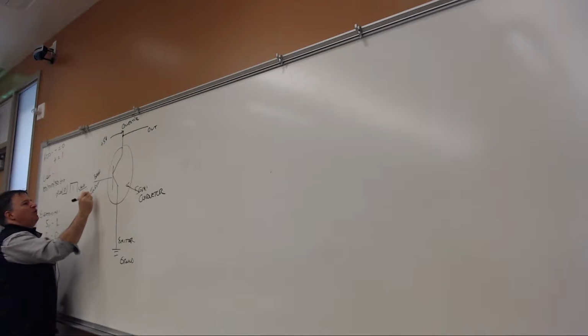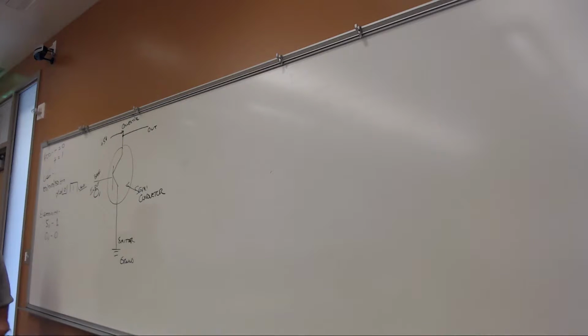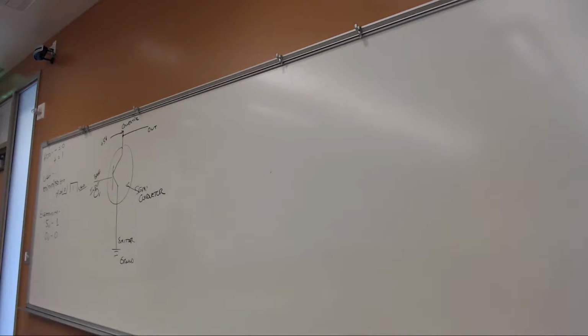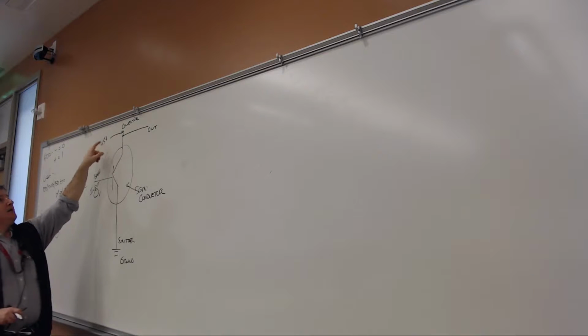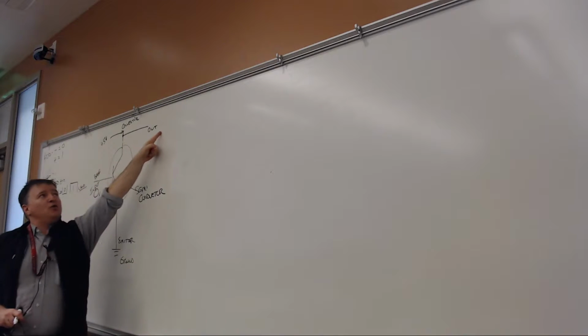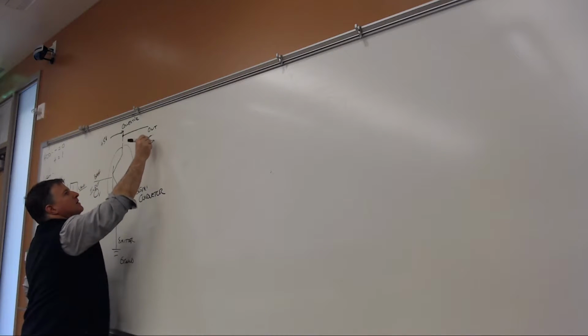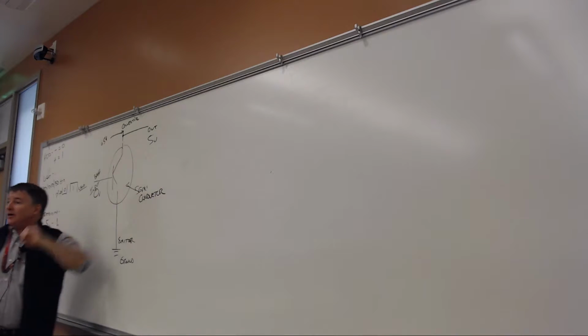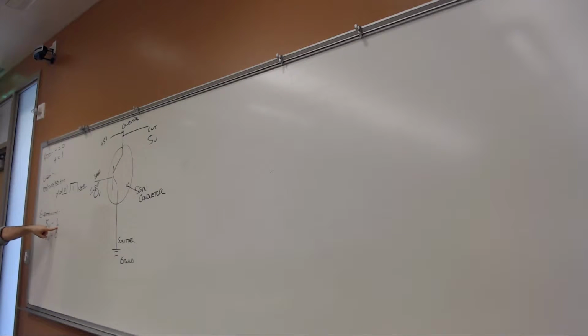When there is 0 volts applied to my semiconducting material, it acts as an insulator. Okay? It acts as an insulator. It's a path of great resistance. So this 5 volts that I have up here being applied to the collector, it won't travel through my semiconductor. It'll go through this wire to seek ground another way. So if in my input I put a 0 in, I get 5 volts out. So if I put a 1 in, I get a 0 out.